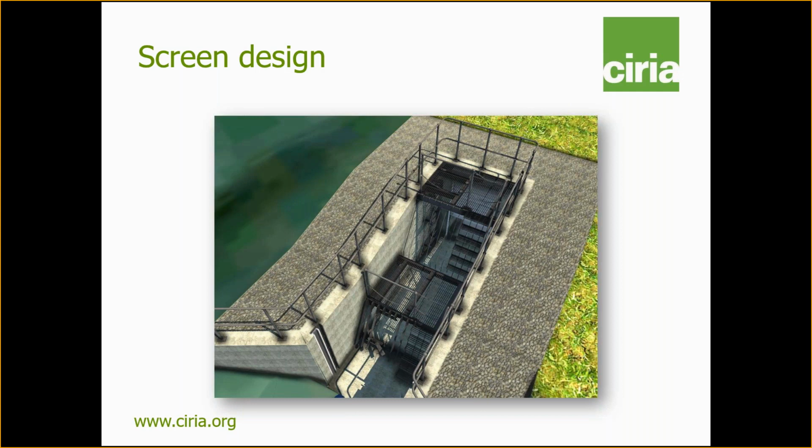As we've already discussed, there's greater recognition of the safety risks involved in manual screen clearing. So screens should be cleaned by methods other than manual raking if possible. Preferred design features include two-stage screens that allow easier raking, a wider bar spacing that traps less debris if that's compatible with the design objectives, and removable rails that allow access for the removal of large items. What we don't want to see are things like horizontal bracing members, which can impair raking, and large gaps between the screen and head wall, which can create a foot entrapment hazard.